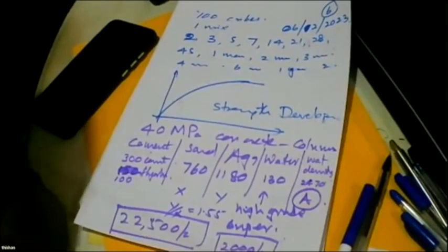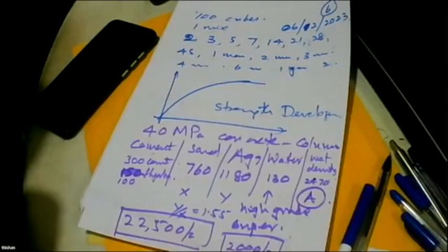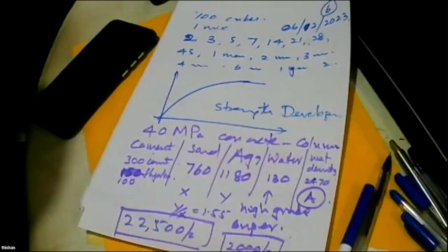And then even a consultant cannot say, I have read this literature and that literature. Why? Because the contractor has a curve that he has developed with his own testing. And if the consultant challenges, he can cast a few more cubes and show that that curve also coincides with the curve he has. So the moment it's verified for about 1 month, the consultant will have to back down.